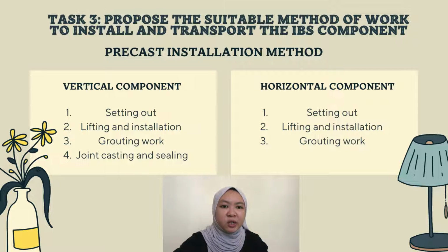The third one is joint casting and sealing. Place and lap the rebar as needed for the component with cast in situ joint. Set up the formwork for the casting joint and pour the concrete. The form is removed after the strength is as required. SCJ Concrete Bukit Gambir plant, which is quite close to the building site, has been chosen as the concrete batching plant.